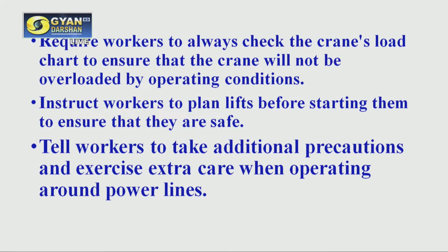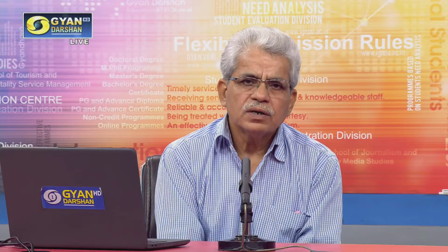Then we should require the workers to always check the crane's load chart to ensure that the crane will not be overloaded by operating conditions. Because many accidents have occurred for this reason, where cranes were used for lifting or transporting loads more than their rating capacity.